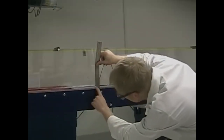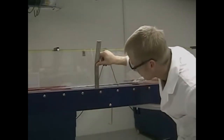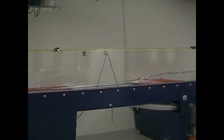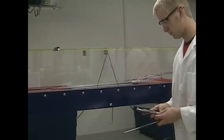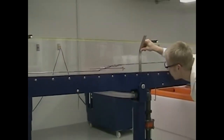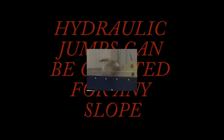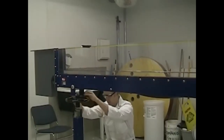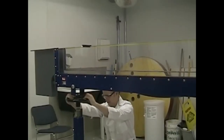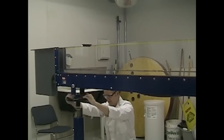We can now verify the height of the jump by first taking a measurement of the upstream depth, or the depth in the supercritical section. Using this depth and the flow rate, the depth downstream of the jump is calculated. This can then be verified with measurement. We are going to increase the slope. Take a moment and decide whether the critical depth line should be raised, stay the same, or be lowered.